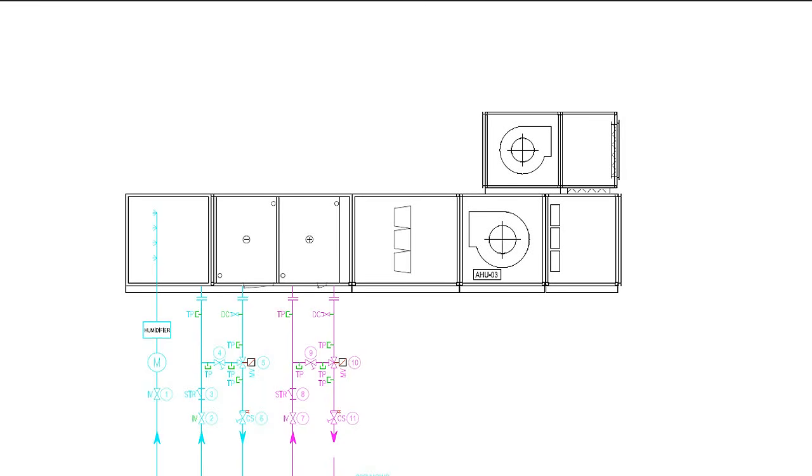Now, a schematic drawing of how an AHU will look is something like this. In this example, the air is flowing in this way, and it goes through the filters. The fan is pulling that in. You've got the bag filters there, and then it passes into the heating coil. You can see that because it's a plus, because it's adding energy into that stream of air. Next, it will pass directly into the cooling coil, and you see that because it's got the negative, because it's taking energy out of that system. And finally here we've got another point, which is the humidifier.